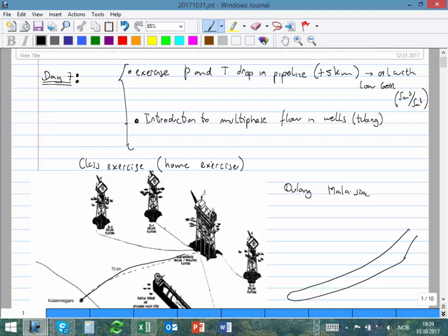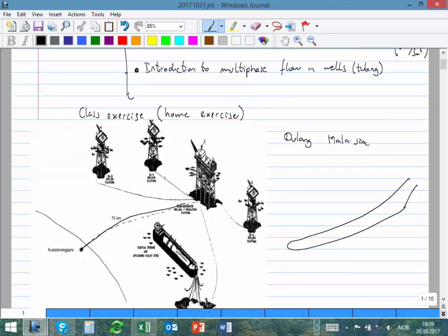Okay. Today we looked at one exercise just to cement your knowledge on liquid flow. We said it's a pipeline of oil. We have to take into account first the compressibility, because the rate in standard conditions is not the same as in local conditions, and also we have to take into account the viscosity change along the pipe.